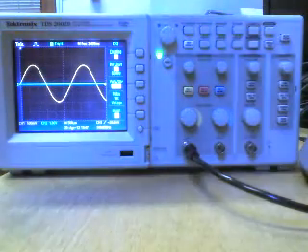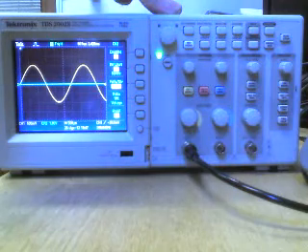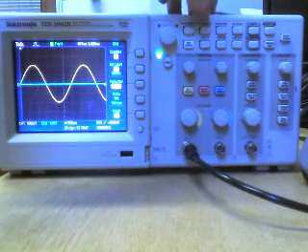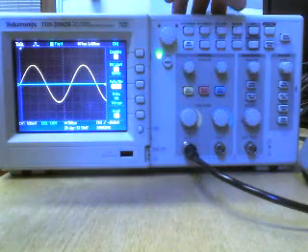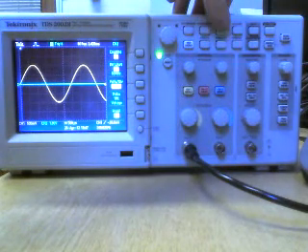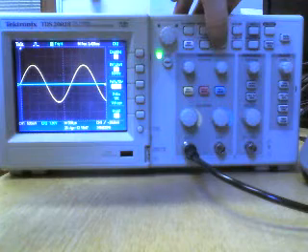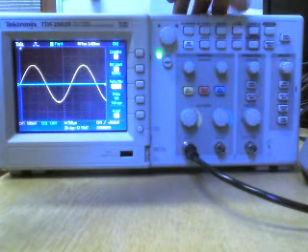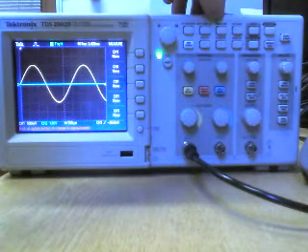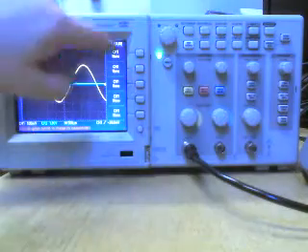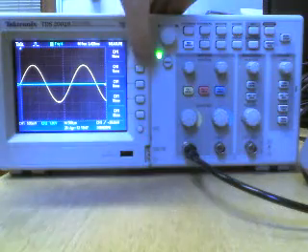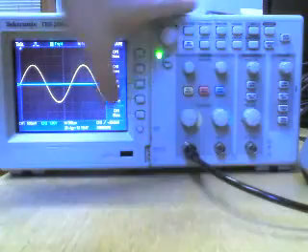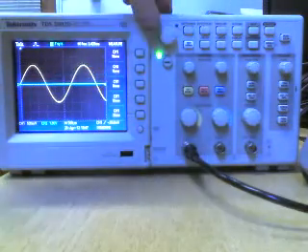Now then, a few little extras which the analog scopes don't have, and this can actually measure your voltages directly. So what we can use is measure or cursor. We do measure first. We press the measure button, it changes our menu down the side to the measure functions, and each button next to each one controls what we want to measure.